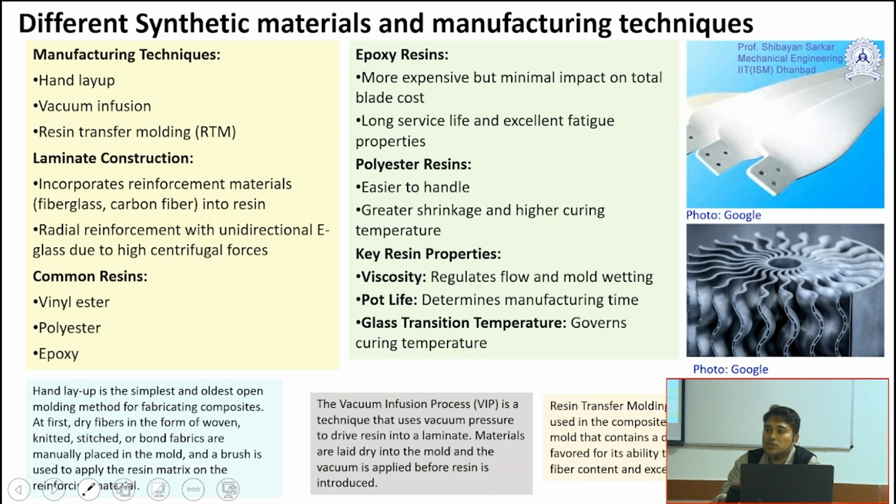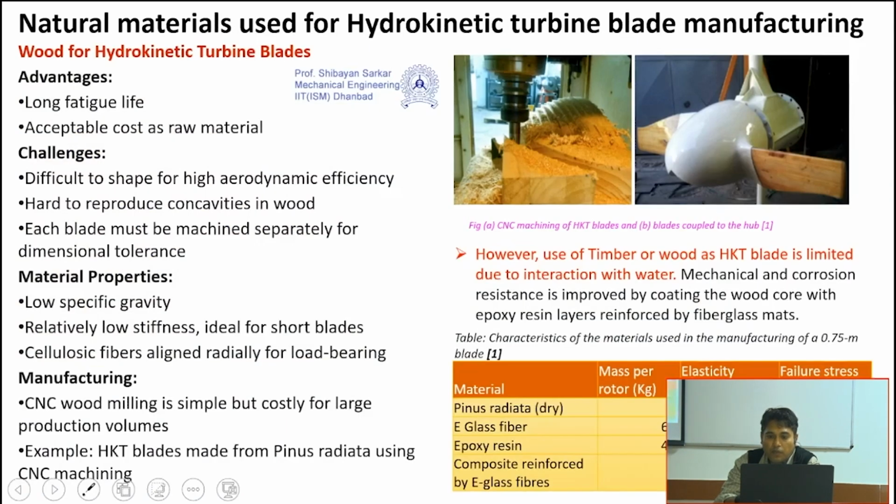All these things are very much important while you are selecting a material. Suppose by observing a material property, suddenly you cannot decide that that particular material will be suitable, because suppose you have designed and you have found a few design parameters, and you have got the magnitude of those design parameters, and accordingly you have matched some of the materials. But whether it is easy to prepare the kind of shape which is desired or not, that is also a main problem. So that also you have to consider while you are selecting.